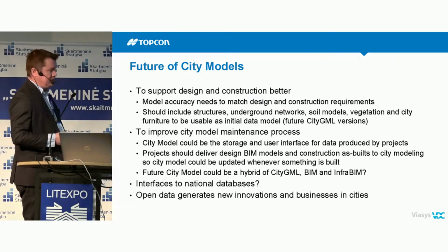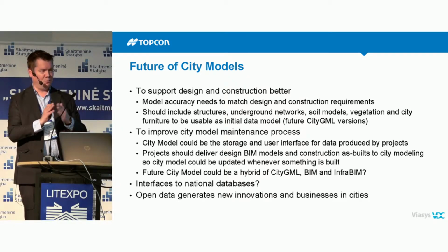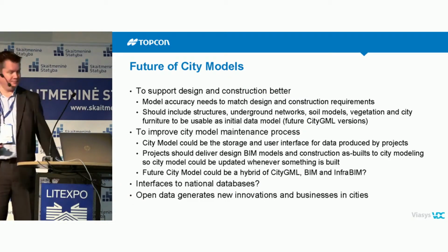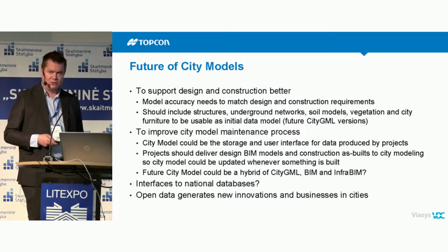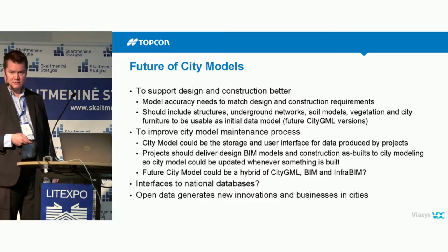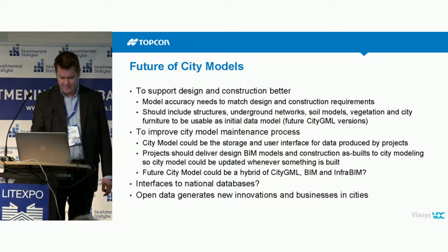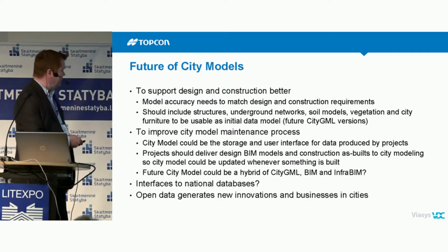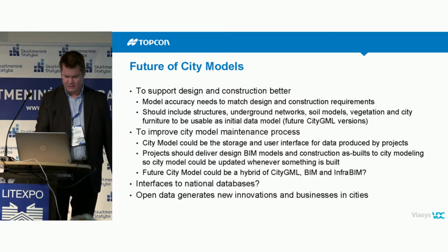City maintenance process, how to update the city model. So don't only make a city model once, you need to think about the continuous update of the city model. And thinking about the city model, it may not be useful if you only have a CityGML city model. It could be a hybrid database, because BIM, IFC and LandXML have much more information than CityGML for certain elements. So you need to think about different disciplines, how you represent them in the city models. Open data. So if you make a city model, make it available, that will generate new businesses.